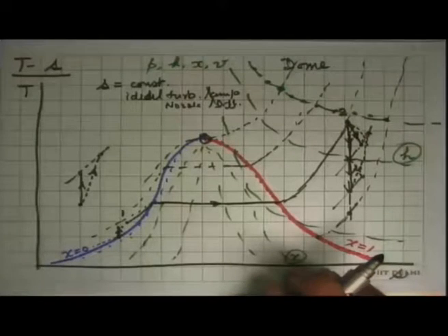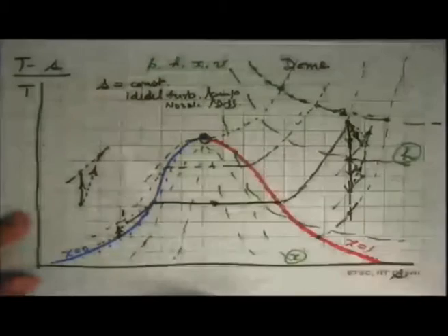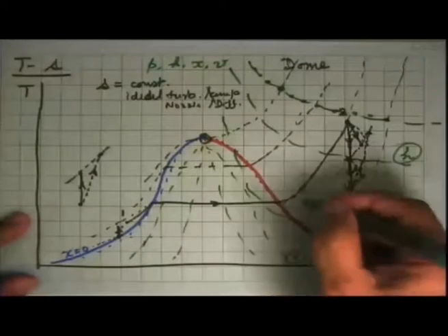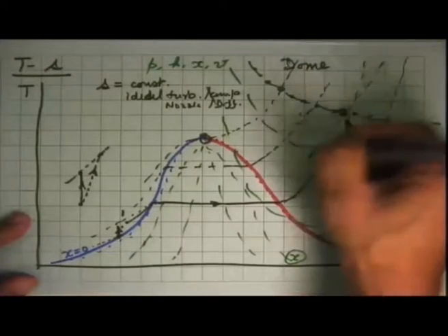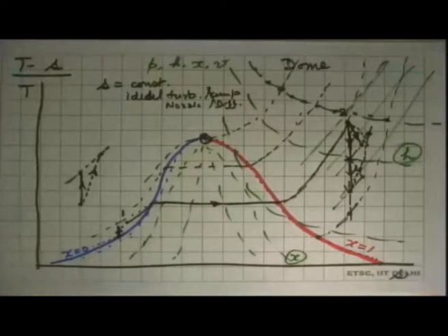You cannot throttle a substance to a higher pressure. It is always to be throttled to a lower pressure. So these are constant enthalpy lines. Specific volume lines are also somewhat similar on this, but of a different slope. So that tells us everything that we wanted about the TS diagram.